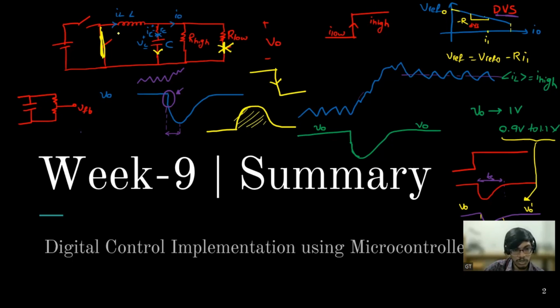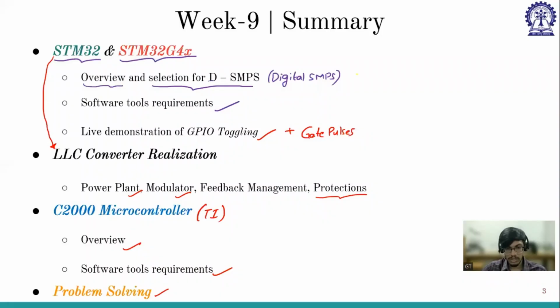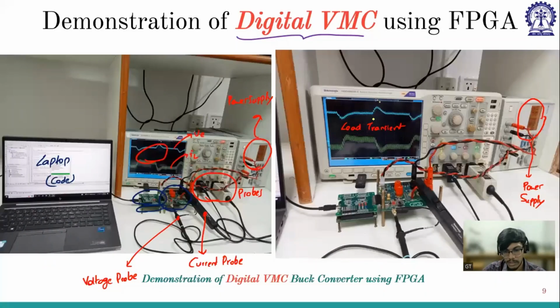And that extra charge it will use to, so whenever these are conducted, the capacitor has more charge, so the inductor will try to discharge, and accordingly the inductor current will come down. Until the inductor takes over, the capacitance will take the charge, and again it will dissipate through the inductor to the load. So the same thing here, the inductor takes some time to deliver that power. So the capacitor will deliver that power, and there is an undershoot. Here the inductor will take some time to absorb that power. So the capacitor absorbs that power, and there is an overshoot. Okay.